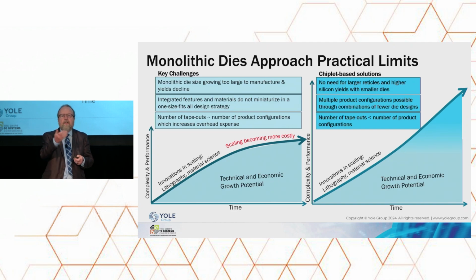With smaller dies, you can take more advantage of the wafer, less waste on your wafers. And in terms of yield, if a small functional value of the final chip solution is defective, then that's much less cost to replace that smaller functional chip than it is to replace an entire system on chip solution. So in terms of waste, in terms of yield, the chiplet technologies are going to have a huge advantage in terms of keeping yield costs optimal.